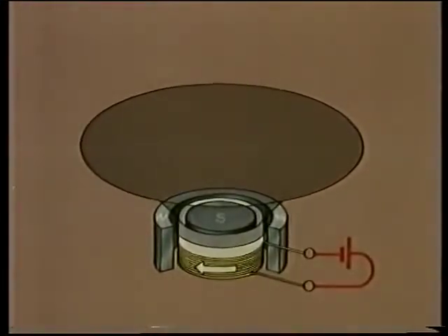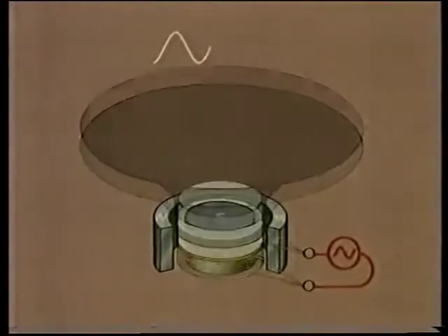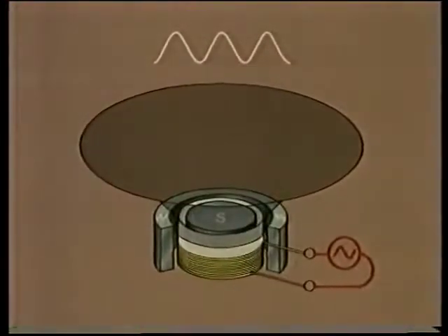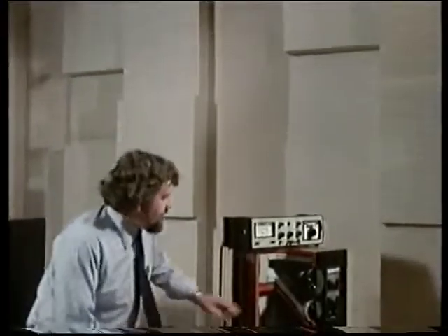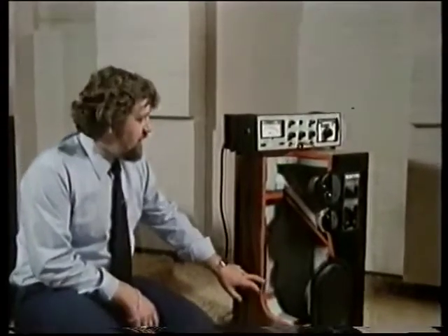Now, if a varying voltage such as a sine wave is applied to the coil, the cone moves backwards and forwards, producing a pressure wave which can be heard as a sound. Well, now let's have a look at a real system. This is a cutaway cabinet, and we can see the 3 drive units inside.